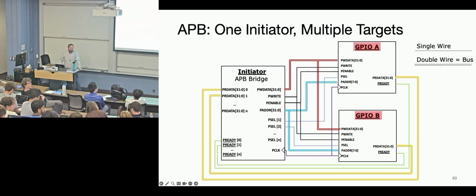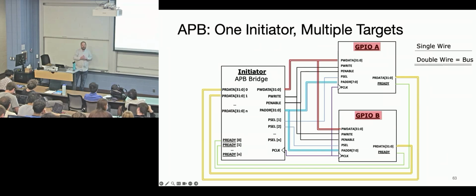Yeah. Going back to the D flip-flop, is the asynchronous clock the biggest use case for that, or are there other design considerations and reasons why I would want to use a D flip-flop? Yeah, it's usually that there's an asynchronous clock or just asynchronous events. Something could happen on a clock edge, and that could cause metastability. If things are synchronized with a clock, you don't have to worry about that.